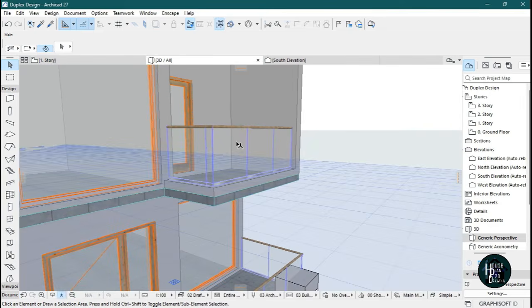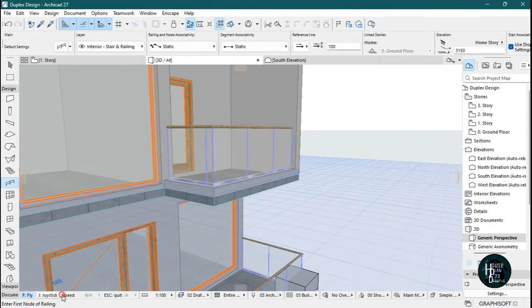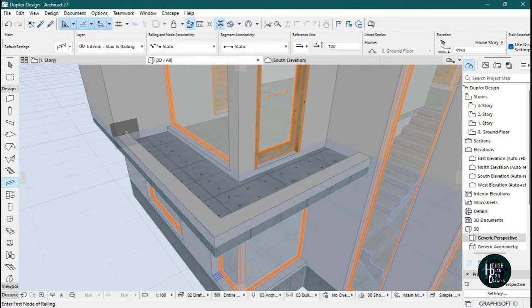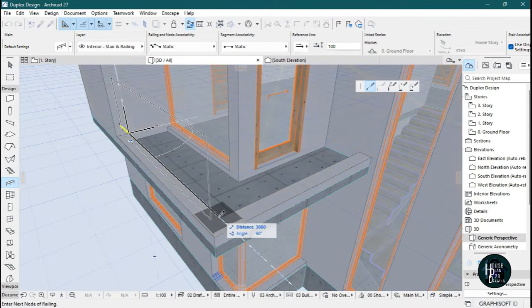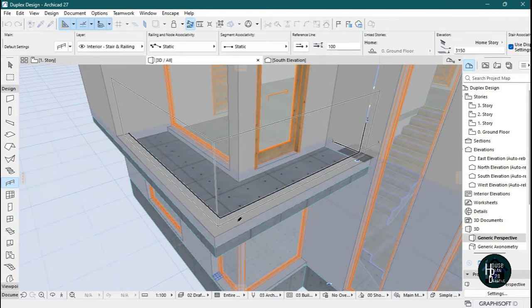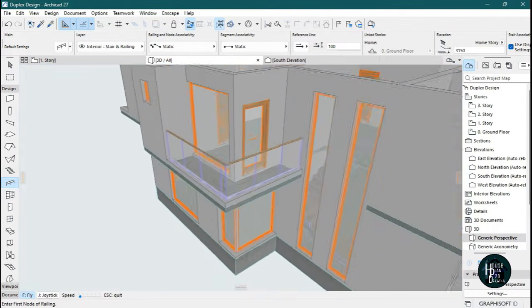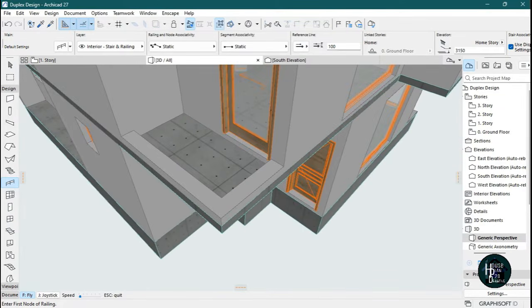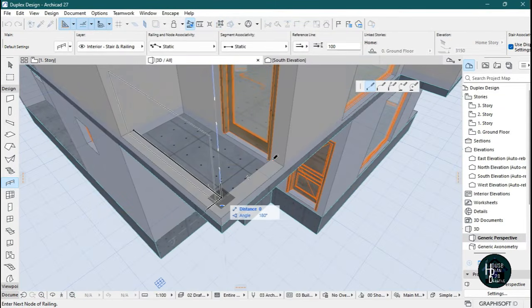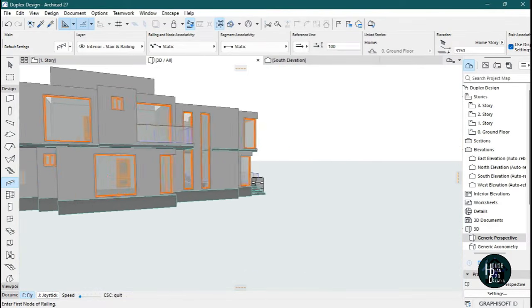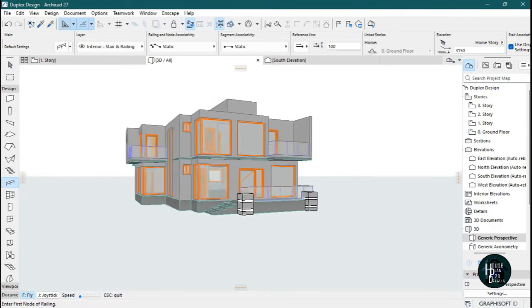So concerning this, the railing has to be there, so I'm going to hold down Alt, select on this railing, and I'm going to move. I'm going to come here. Okay, click. I'm going to click this point here, then double click on that side, so I can have the railing on, as you can see. So I'm also going to fix that for this other side too. All right, so we are actually heading somewhere.